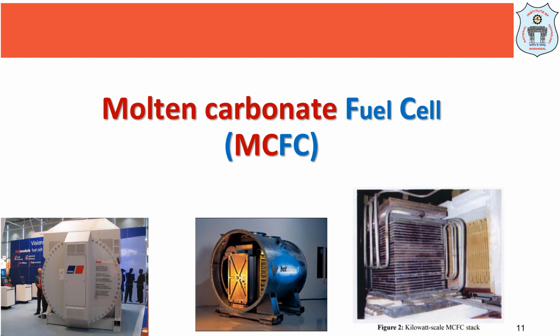fuel cells. These molten carbonate fuel cells have recently been identified as another powerful technology which can easily capture the CO2 from the flue gas produced by coal or natural gas fired power plants, or even from the cement industries, because they have the advantage of also generating very low carbon base load electricity and high grade waste heat. The reaction taking place here is endothermic, which we are going to discuss in detail. For this endothermic reaction we have to supply heat, right? That heat is supplied from the waste heat produced by the fuel cell.